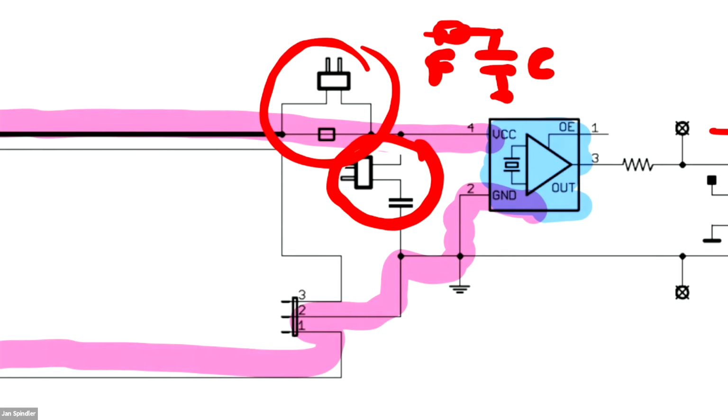The ferrite and the capacitor have 2 jumpers, so I can introduce or remove the decoupling circuit easily. It's a very bad situation because the jumpers introduce a lot of inductance. But for the demo, it's the best option. Now there is no decoupling network.